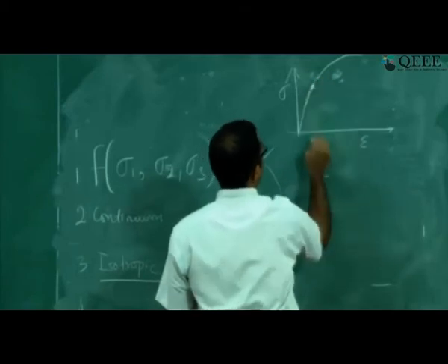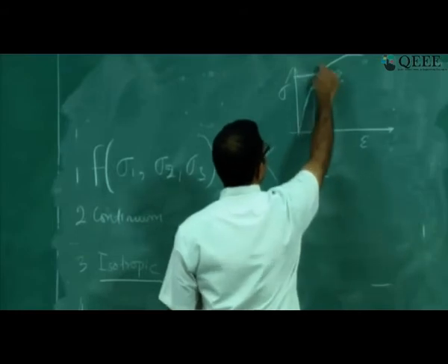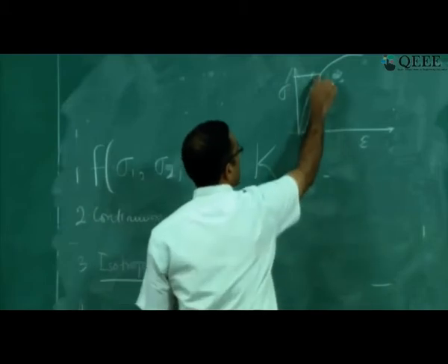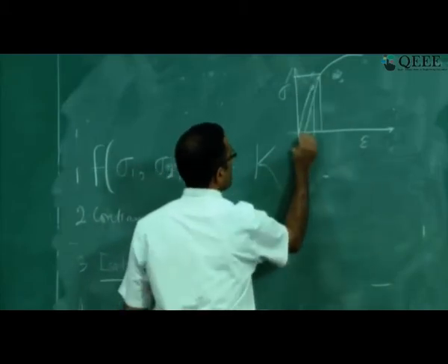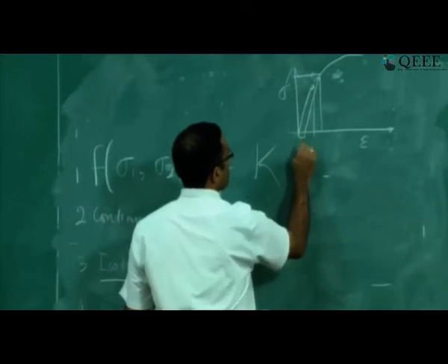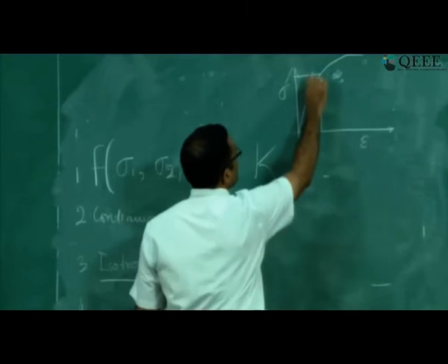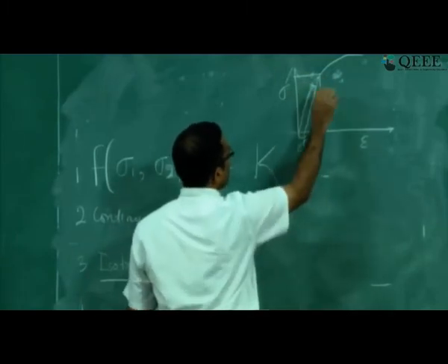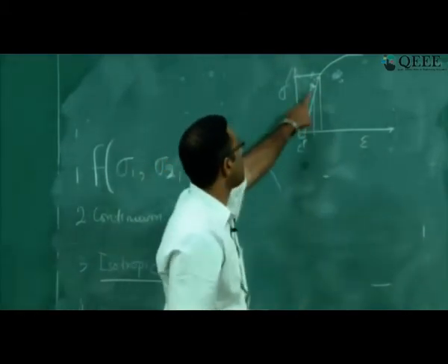Beyond this, if you apply any small strain, the stresses are going to increase, and if you unload it, it will unload along this line parallel to the Young's modulus line, the linear portion here, and this is called the permanent strain or the plastic strain. We don't care in this course about what happens when we cross this spot. We are only going to be able to identify this spot, that's it. Once it has reached this spot, our material has failed.